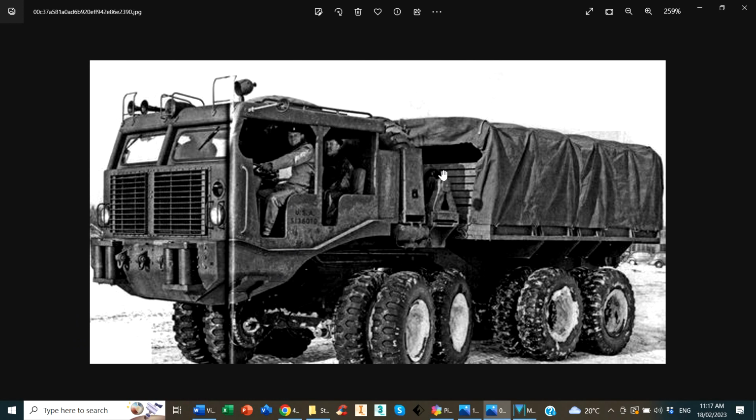This is a Sterling T26, experimental US military truck from the 50s, I think. Slow speed, heavy load carrier. But if you look carefully, you'll see that the front bogie is steered, not the individual axles. Again, simple drive axles, non-steering, but put on a bogie frame that can steer. And that's typically called wagon steering. It does have uses today, but generally speaking, vehicles run at higher speeds than would be permissible with this sort of application on a truck.